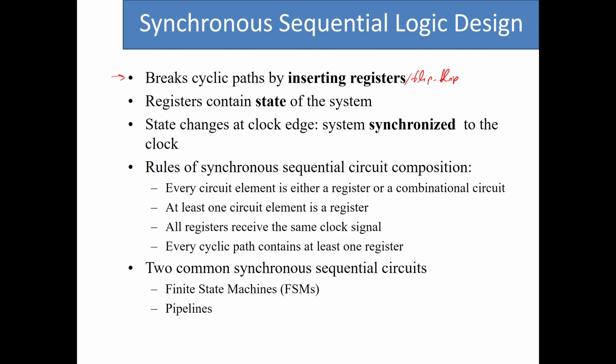Any cyclic path in the circuit, in order for that circuit to be considered a synchronous sequential circuit, needs to contain a flip-flop. Without that, it is an example of an asynchronous logic circuit. So that is a very important thing that we need to consider.